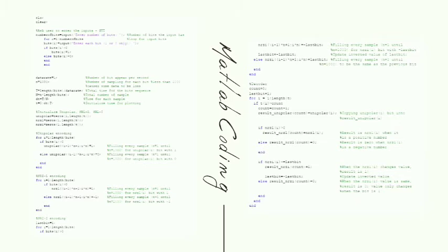Next we have the decoder, where we set the count equal to 0 and the last bit equal to 1, because we need to use the last bit once again. We do it in a loop, just like for the encoder. The line coding program repeats until it completes the cycle of the total number of samples. Then we update the count value. For the unipolar decoder result, it will just copy the unipolar line coding output. For NRZ-L, if the line coding output is greater than 0, it will just copy, but if it is not greater than 0, it will change the NRZ-L output from -1 into 0.